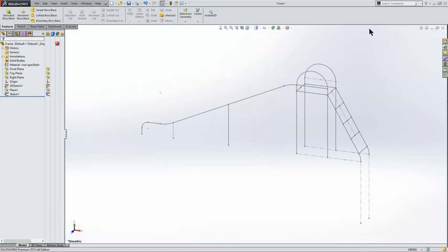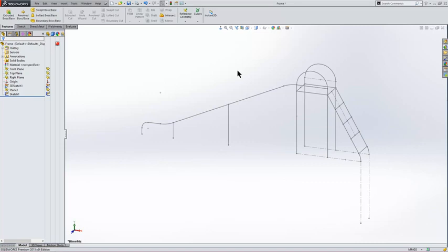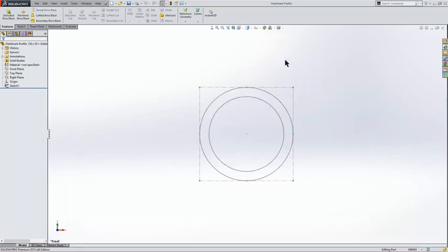weldment. Now, to do weldment profiles, normally you'd use your standard ISO or BSI or ANSI inch weldment profiles. But actually I want to create my own custom one. So I've gone ahead and created a sketch for my custom weldment. It's hollow in the middle and has a thickness of 5 mil.